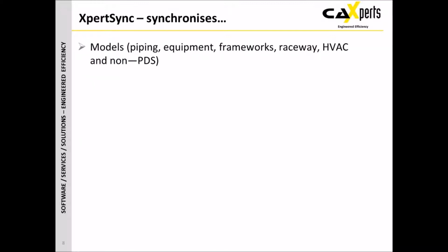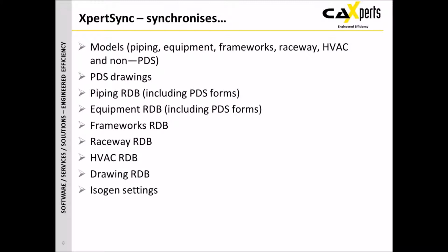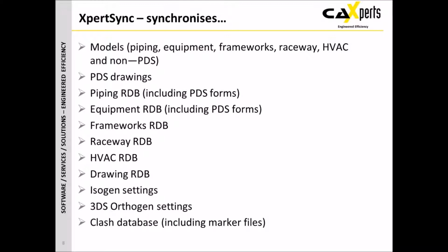What it synchronizes is models, that's the piping, equipment, frameworks, raceways, HVAC and non-PDS models, PDS drawings, the piping RDB, equipment RDB, frameworks, raceway, HVAC, drawings, isogen, orthogen, and the clash database, including marker files.